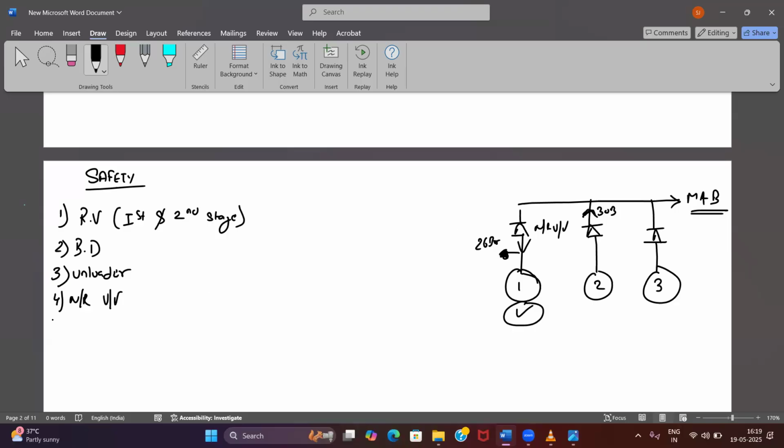I will take it in a little more detail. Then you have, nobody said, lube oil low pressure alarm and trip. You have an attached gear pump with the crankshaft, which is generating lube oil pressure. Okay, lube oil low pressure alarm and trip. Lube oil high temperature alarm and trip.